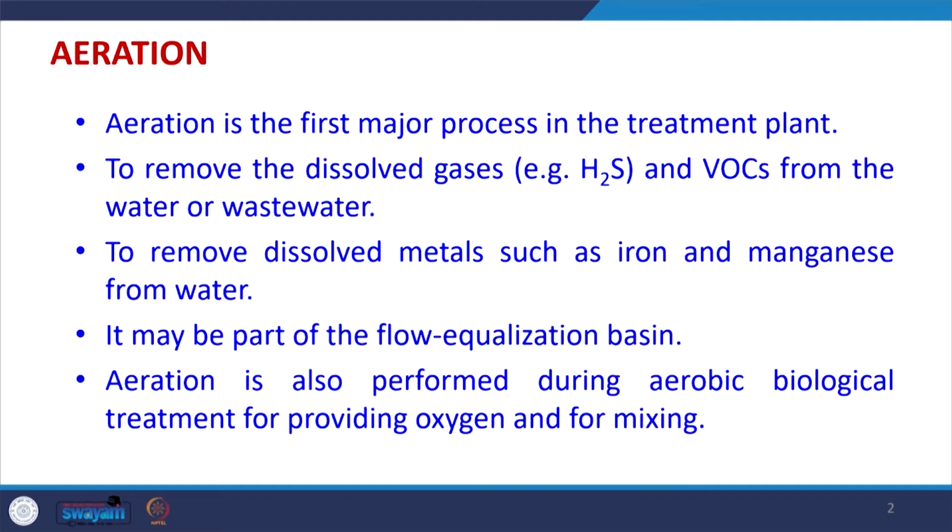So, and we have to use it further for drinking. Similarly, a lot of wastewaters which are discharged from various industries may contain a high amount of dissolved gases. If we want to remove these dissolved gases, we have to use aeration. Many VOCs, volatile organic compounds, can be removed using aeration. Similarly, some of the dissolved metals like iron, manganese, etc., can be removed using the aeration method.